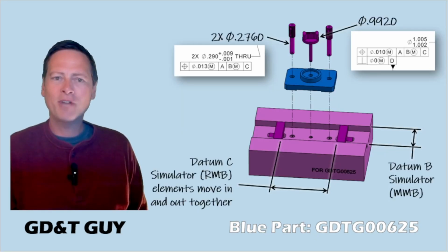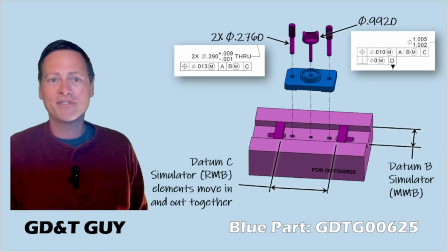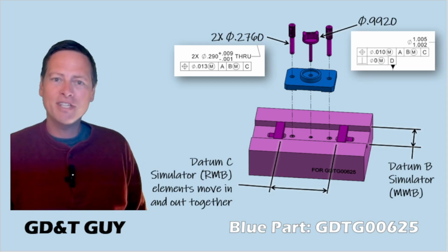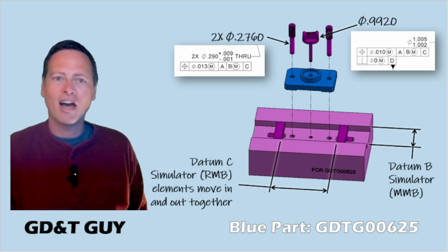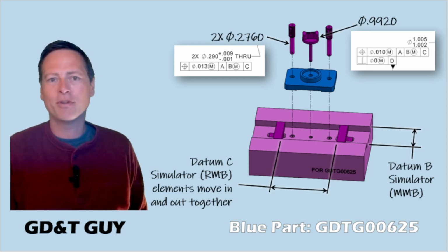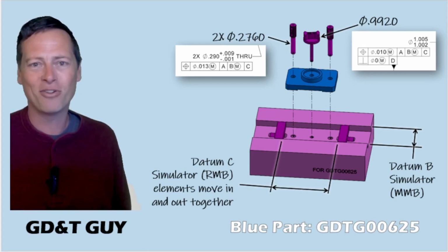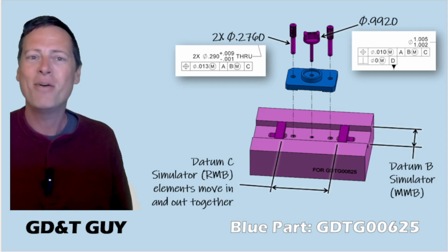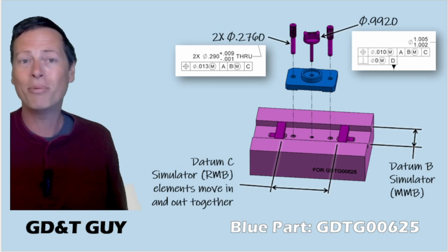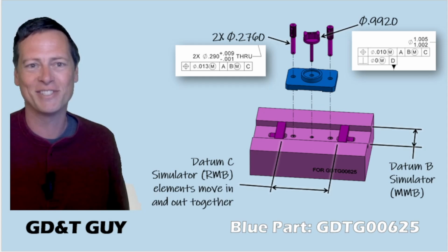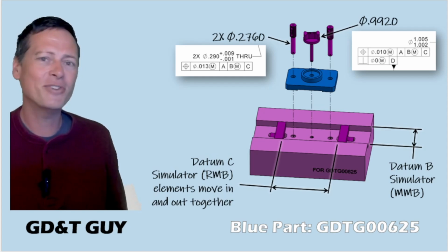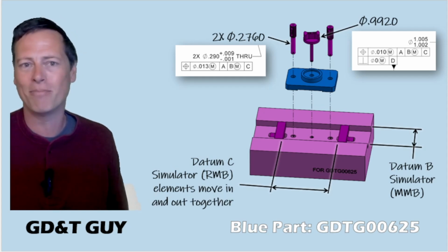Dang. I'm trying to get more perpendicularity control because of the way now, with datum C referenced at RMB, I am going to be gauging in contact with both ends. This would be a pretty exciting, if not outright fanciful gauge, but fun to think about. Probably it's the case that all of these gauges are fanciful. In a way, it's really too bad how few of them ever seem to get made because they'd be so much fun.